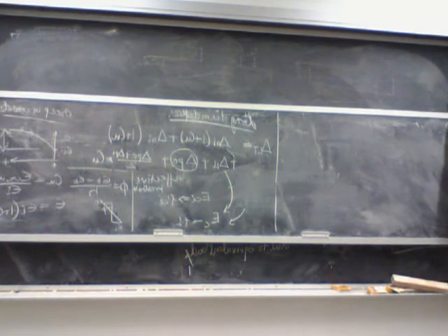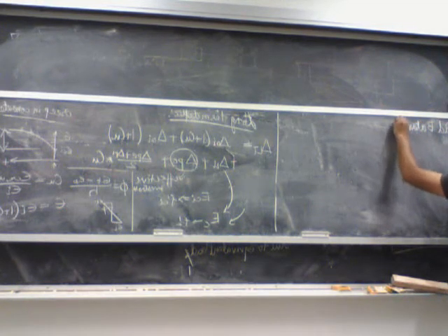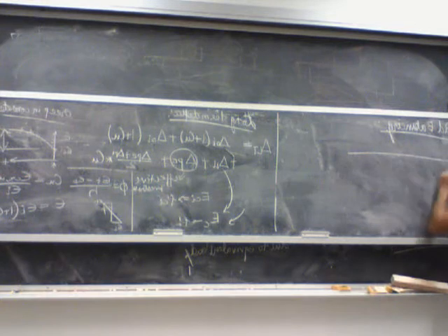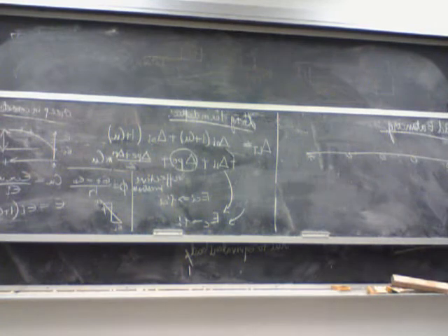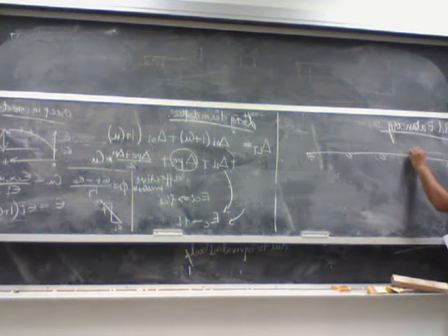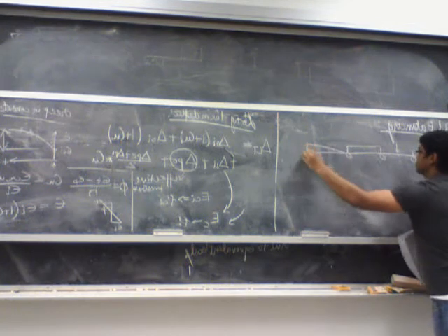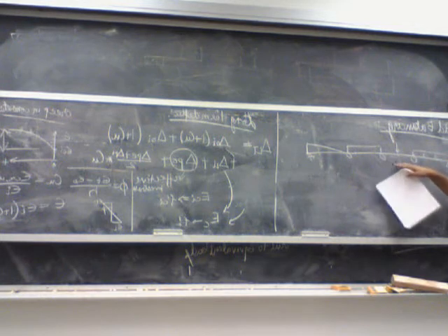So again, depending on what kind of profile you need to provide, let's say we have to do the load balancing to find out your Fi and E naught. Let's say it's an indeterminate beam. And in the problem statement, it will tell you what is the actual load that needs to be balanced due to the prestressing force and the eccentricity. So it can say that you need to balance a distributed load on this one, a point load on this, distributed on this one, and some weird load on this one. We won't give it to you in the exam, but let's say it's given this way.